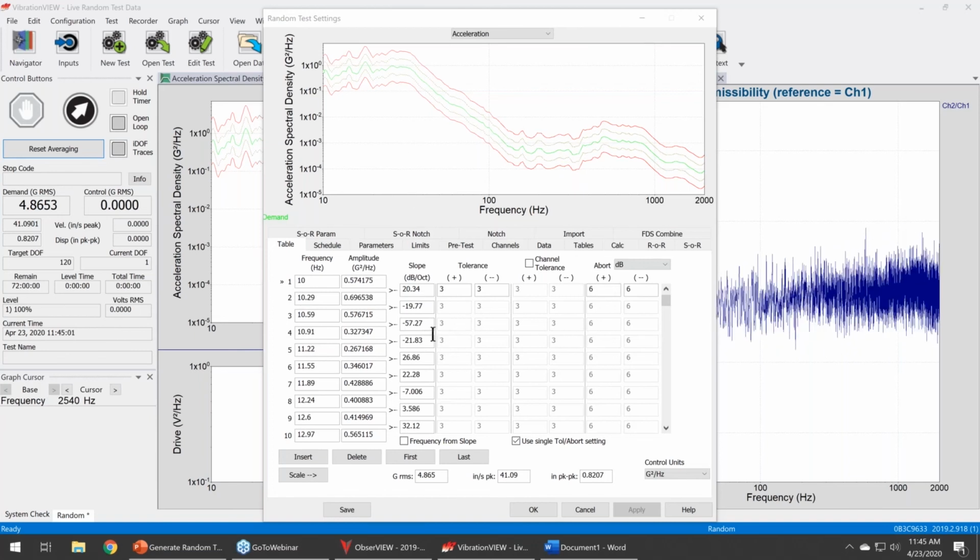What are some examples of real life factors that help you determine these target lives? That's a great question. If you look at automotive companies, they have estimations of the test track data and what contribution that has to the lifetime of the product. So they know that 20% of the lifetime of the product is going to be on rough road, 10% on Belgian block, 40% on highway at high speed, whatever it might be.